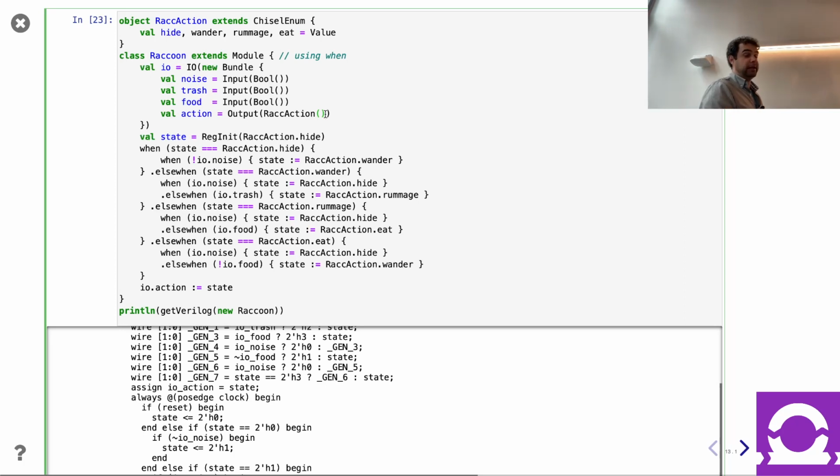Yes, exactly right. So if I keep this type here, things connecting to that also need to have that type. That's the point of both Chisel and Scala in general, the way you're typing: you want things to be very knowledgeable about the types they're working with, and if the types don't match up, you want it to tell you, hey, they don't match up. Usually humans should figure out, okay, I should change this one, or perhaps I should do a cast, etc. Like I said, when you write C, it's very permissive, right? You can have an int, a long, a uint64, whatever, they're all okay. Here it's like, no. These need to be the same. And if they're not the same, it tells you that you need to fix it, right? That's the whole point.